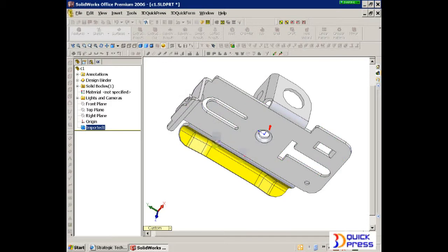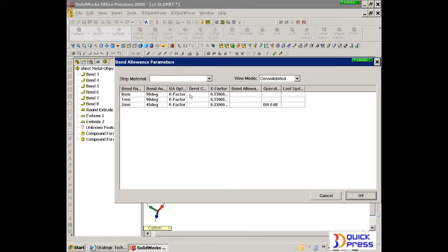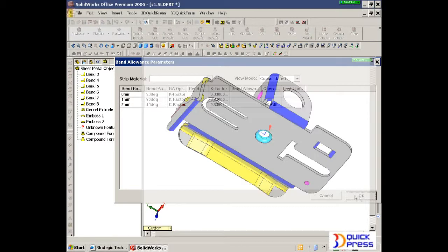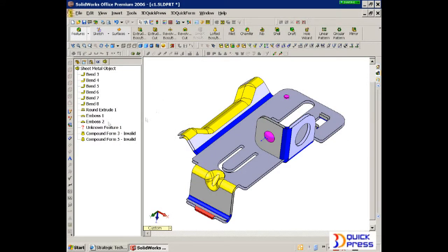Of course, all the bend compensation can be adjusted per feature. Let's find those features first, which is quite unique. So it does feature recognition. It gives me a bend report. It highlights the areas it can unfold. As you can see on the left, we now have an unfold manager. So instantly we get features that we can unfold.